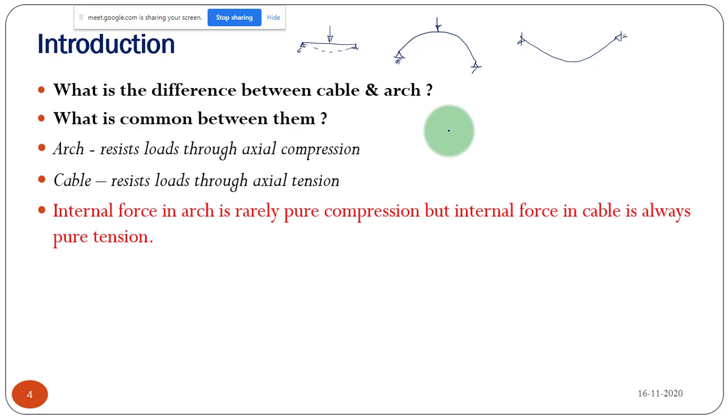But for an arch, it can experience tensile force, but mainly only compressive force will be there, because it is something like a hog. You can say that the shape will be hogging, right? So to have some tensile force, we have to apply some more load. Once some hogging moment comes, then only the tensile force will come in the arch, because of its shape it is already having some rise. Because of this rise, in arches mainly only compressive force will be there.